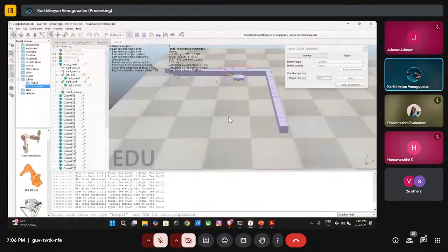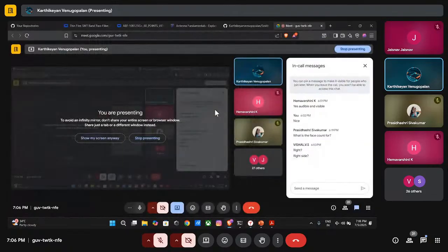But can you say what the disadvantage is here? It's obvious, right? We have to go for one complete rotation to check whether the termination point is there or not. So this is going to waste a lot of time on one complete rotation over the obstacle. We have to make the bot follow it.